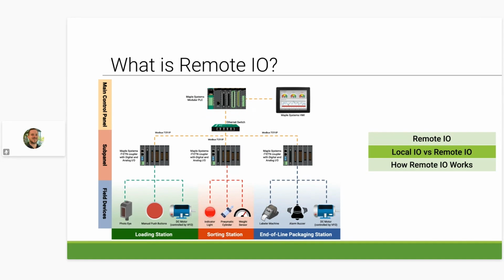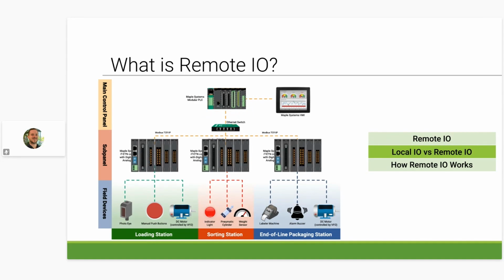For remote I/O, devices can be located much further away from the main controller. This offers an increase in flexibility across larger or more complex facilities. With the use of network cables or field bus systems that accomplish the connection of remote I/O, this greatly reduces the amount of wiring required for long distances, which in turn simplifies the overall system architecture. Again, with modern communication networks and Ethernet protocols, the latency from remote I/O is comparable to that of local.